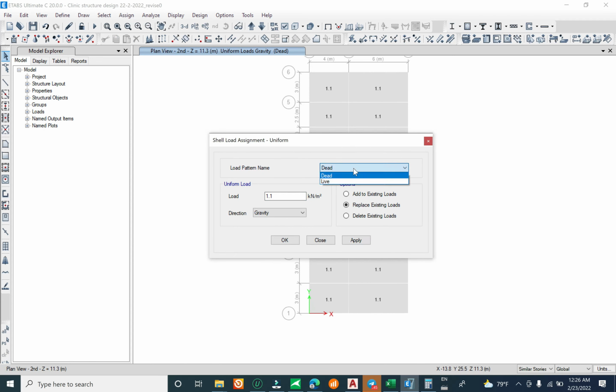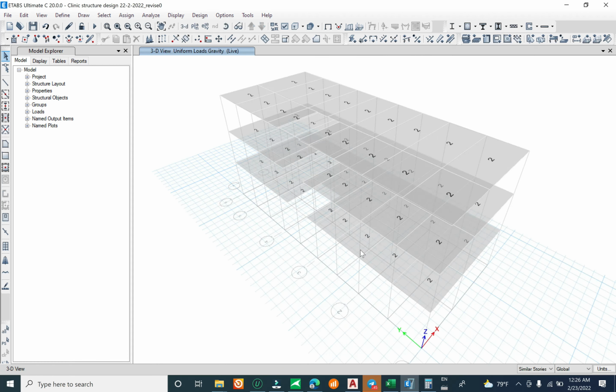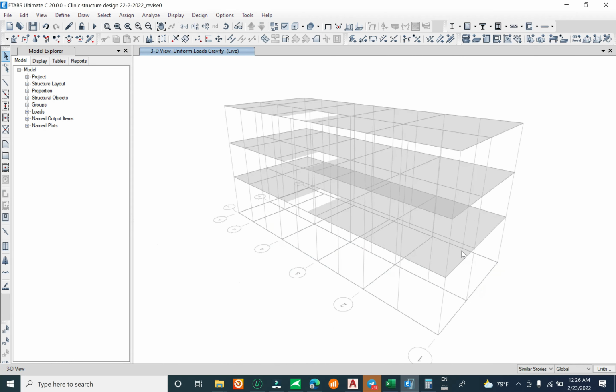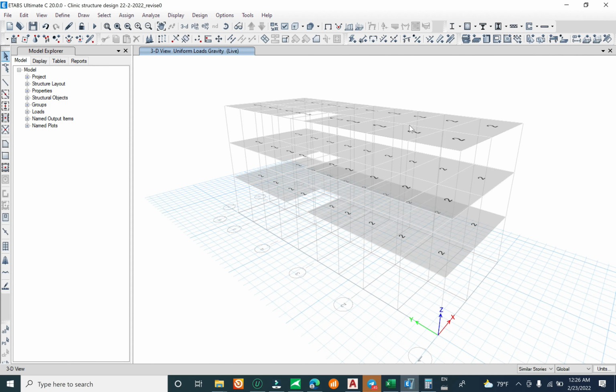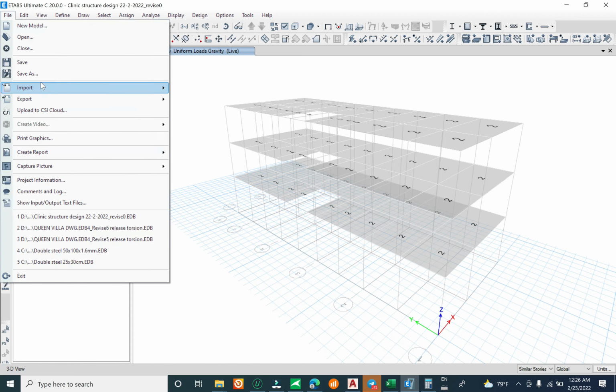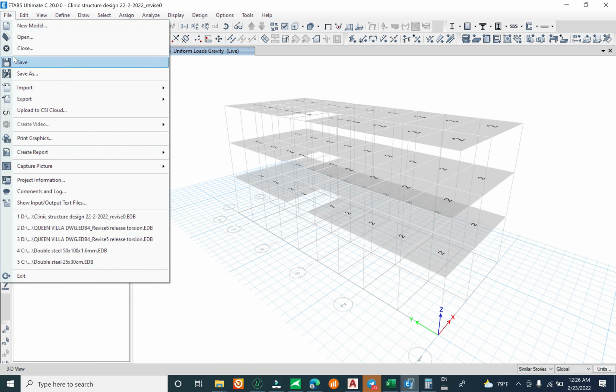And for the line load we select from the previous selection and apply it too. Okay, now you have to check it. We use it for the same because at the top we have other concrete screed, but we do not include it in the link, so you have to include it in the process. Okay, now you have to check it.